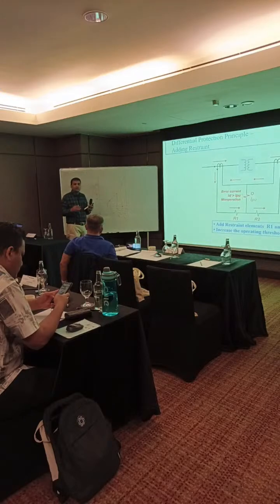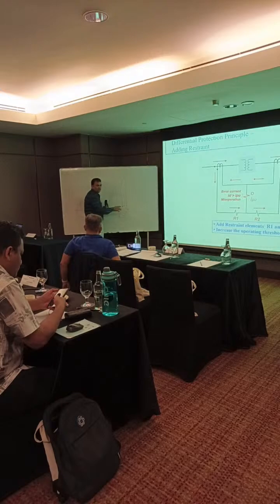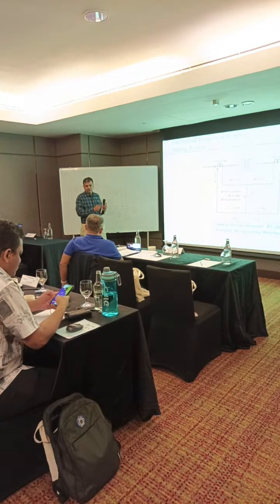So we can start injecting the second point from 1.25 times. The point will be different, but you only need to keep in mind when you are reading the ID and I differential value that it is not starting at slope 2. Because if your I bias is more than 1.5, that means it is slope 3. So you can easily find out from the measurement.